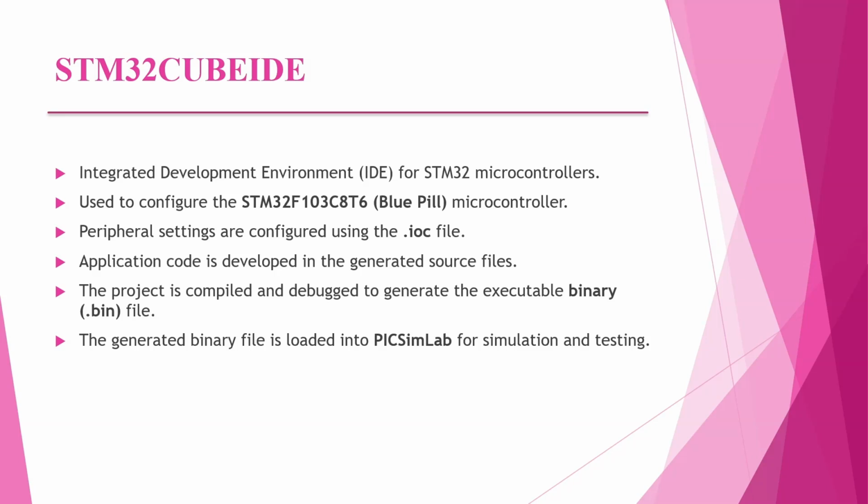So basically, STM32CubeIDE is an integrated development environment, IDE, for STM32 microcontrollers and is used to configure the STM32F103C8, the Blue Pill microcontroller. Peripheral settings are configured using the .ioc file, and in that .ioc file, we see the pin configuration.